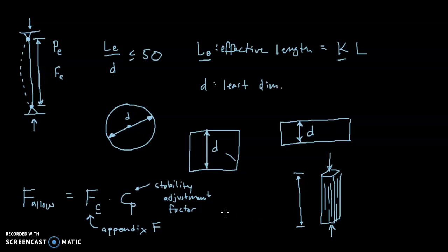So this is just one adjustment factor. In the actual code for designing timber, there are many adjustment factors for things like temperature and humidity, and whether it's a single column or a repeated element like a stud, and many others that I'm not remembering off the top of my head right now. So it all, again, comes down to the behavior of wood. It's a natural material.